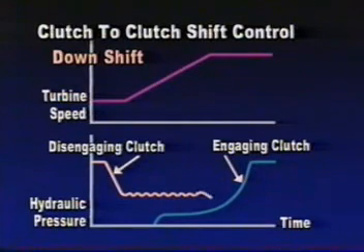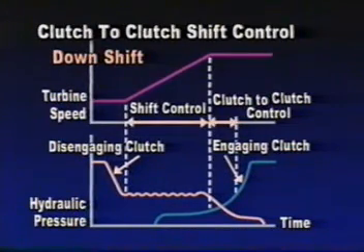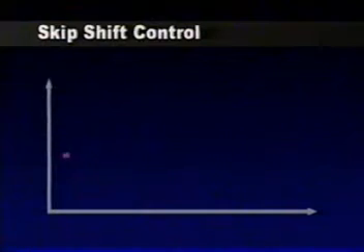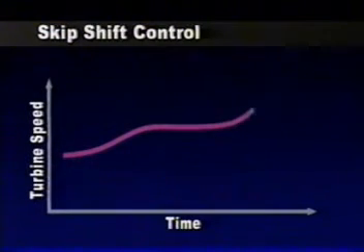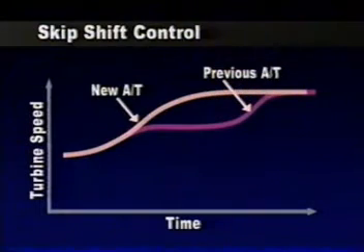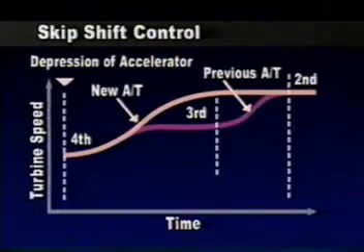So the exact torque capacity of both clutches is calculated for the precise control in release and combination clutches. Response becomes smooth and quick by preventing run-up and brake interlock during gear shift. Solenoid valve is applied to each clutch so that the skip shift is allowed. Its merit is reduced time of overall shift completion.